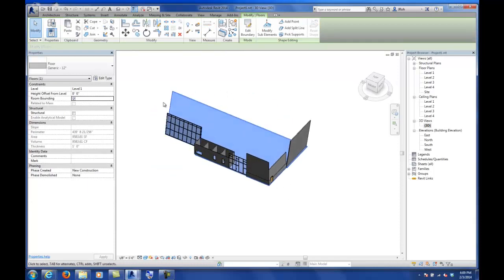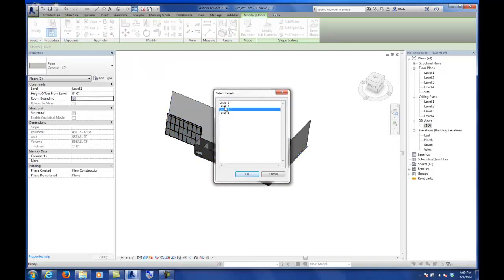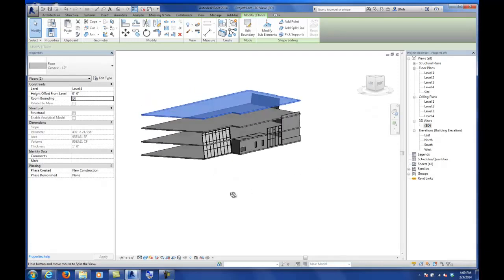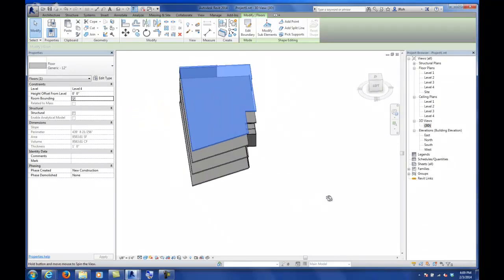And let's say we want this floor plate on all 4 floors, which we probably don't want, but for instance, this particular building is going to be repetitive that way. I could click on this particular component if we're in 3D or in the level 1 floor plan, and hit copy to clipboard. And now we can do the paste with the down arrow and select align to levels, and now pick level 2, hold the control key, level 3 and level 4, and click OK, and it'll copy that floor pattern on all the other levels. So it's a kind of quick way.